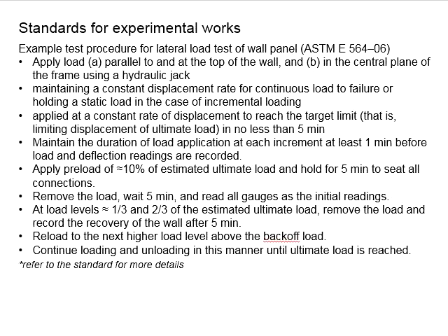You will be able to observe whether there are permanent deformations at the end of each cycle before the next cycle is triggered. You're going to see the ability of the wall panels to recover to their original positions, as well as observe the changes in stiffness as a reflection of the damages that occur during those cycles. And then you're going to acquire the ultimate capacity of the specimen.